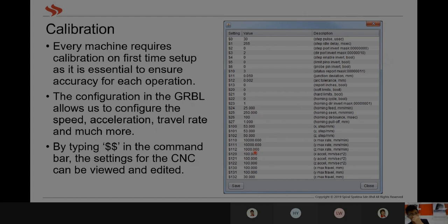So you have to bear in mind that every time you set feed rate, you don't have to go 100% with whatever you see on the net or calculate. You're going to have to depend on your acceleration rate set here. Then you can also set max travel rate to 100. Normally we keep it at 100. If you want to move it more, you can set it more, but 100 is a secure baseline so that you don't overwork the machine.